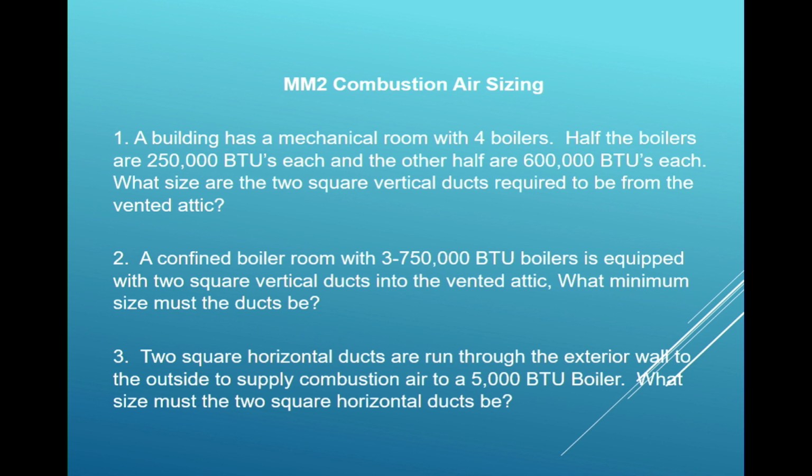I'm outdoors, right? Because it's a vented attic. That's a space that freely communicates with the outdoors. So that takes me to 701.6 outdoors. And then they said it's a vertical duct, so you'd agree that takes me to 701.6, number 1, right? Vertical duct or direct communications. Does that make sense? So again, you see how everything else went away except for that.